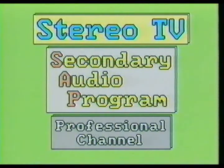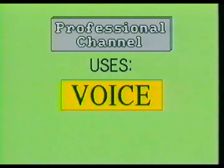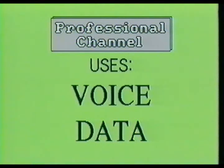MTS also makes provisions for what is termed a professional channel. The professional channel makes possible the transmission of other information not necessarily related to the main TV broadcast. The professional channel could be used for basically anything, such as voice communication from television station to live news crews, or the transmission of digital data for scrambling the picture of the TV channel, or digitally setting a particular mode of operation within your television set. There can be more than one professional channel per TV channel, as long as bandwidth is available.